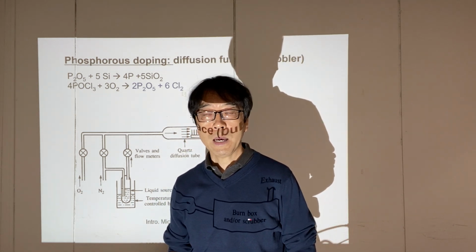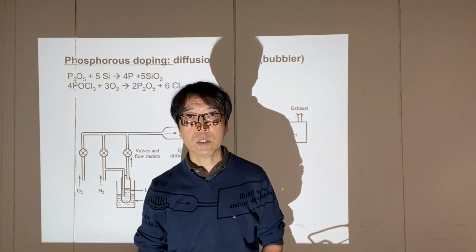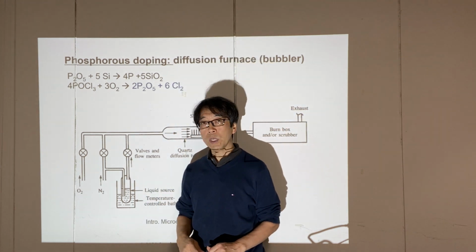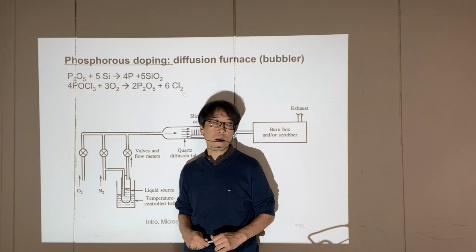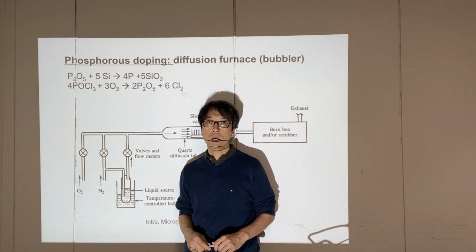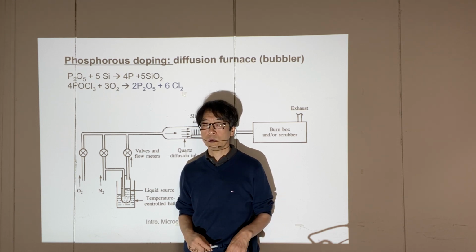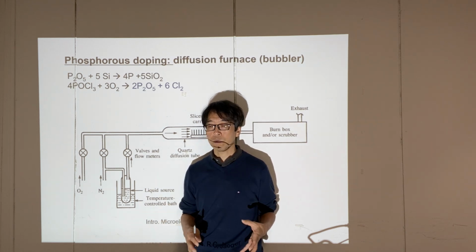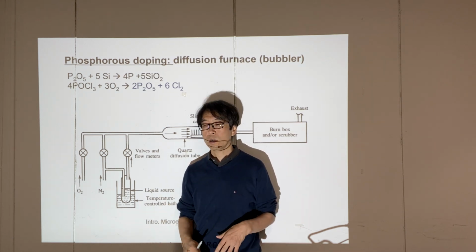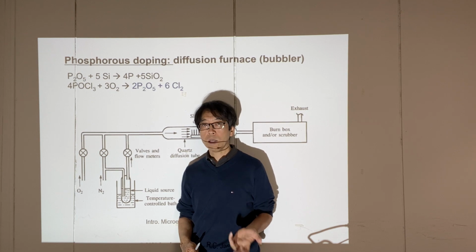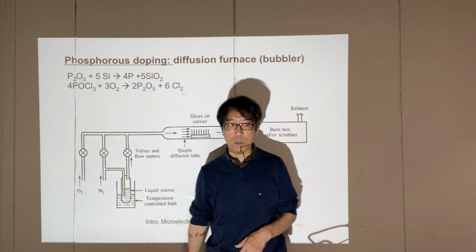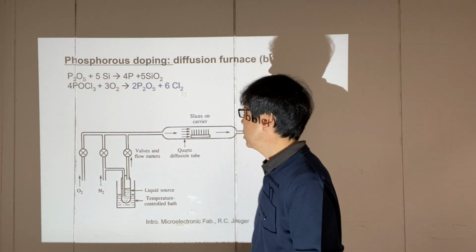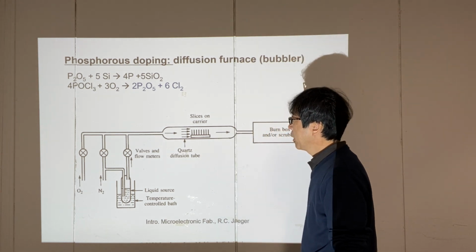There is an MSDS, Material Safety Data Sheet, and you have to read it and understand the danger and the measures against this danger as well. So you need to be very careful about it. In the clean room, we have a lot of measures: many sensors and detectors that can detect a leakage and maybe shut down the clean room. So it's a really important process.